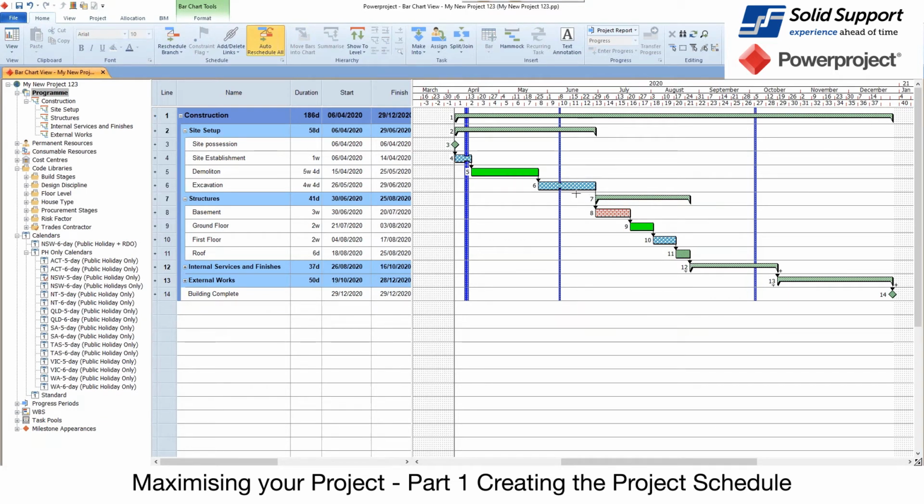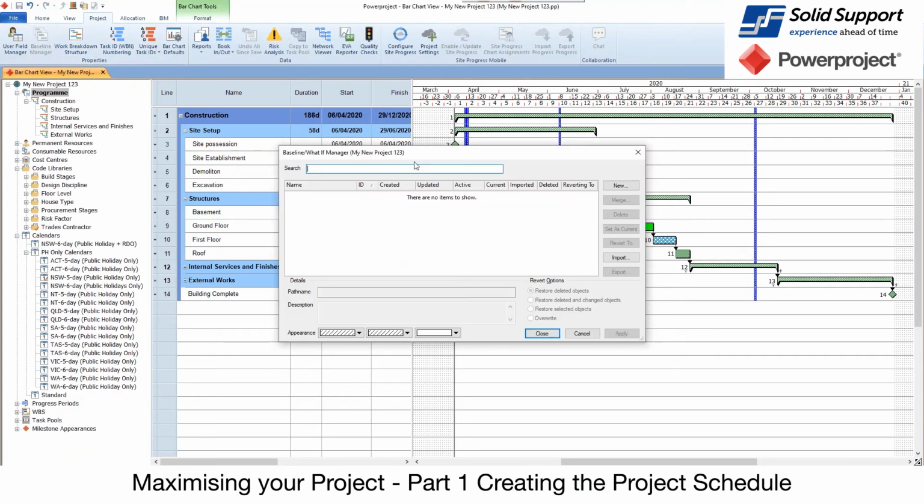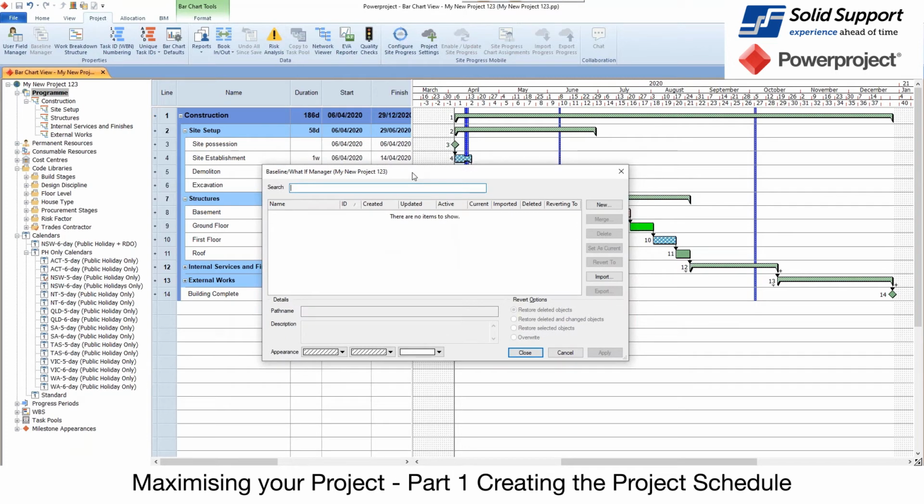Now, when you are making changes to your project and making impacts to it, putting delays in is great, but also knowing what it's like at a certain point. And again, that might be week 1, week 2, week 3, and so forth. So I'm just saving that there. I'm going to go into the project tab and go to Baseline Manager. And inside here, I'm going to click on Baseline Manager, What If Manager for my project. And this allows me to create a snapshot, a baseline of my project.